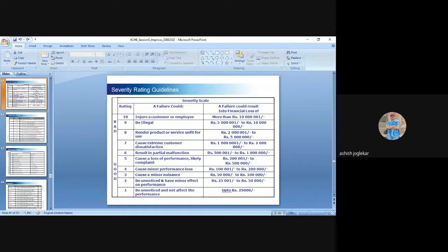So for the severity on the customer that the failure mode has, the team will define it. Your team can say some number, say 5, 6, 7, whatever it is, and that severity is to be rated on the scale of 1 to 10, with 10 being the highest, the most hazardous, most dangerous, most loss-making, with the most customer effect, and 1 being the lowest.